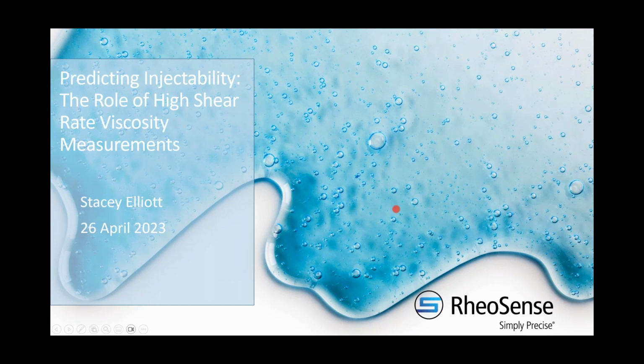And we'll address this a little more later. The microfluidic flow channel is ideal for measuring high shear rates because of the dimensions of the channel. It prevents any sort of turbulence or secondary flows that can be a real problem at higher shear rates in different types of instruments. And also because the fluid is enclosed in this flow channel, you don't have issues of sample flying out of your tool. So when we get into talking about how important it is to get high shear rates so that you can get good predictions for injection force, you're also going to want to consider how you're going to obtain those values.